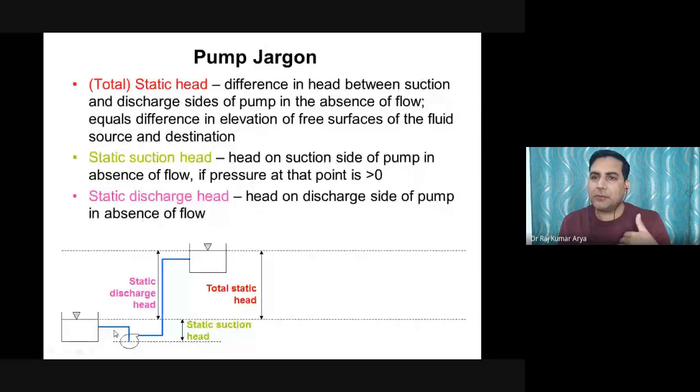This is one of the configurations that happens in industry, and also in households, because we can store the fluid in some particular tank and transmit it from there. That is the one configuration. In this case, fluid is always present inside the pump, so there is no problem. You can turn on the pump anytime. It will always suck the fluid actually.